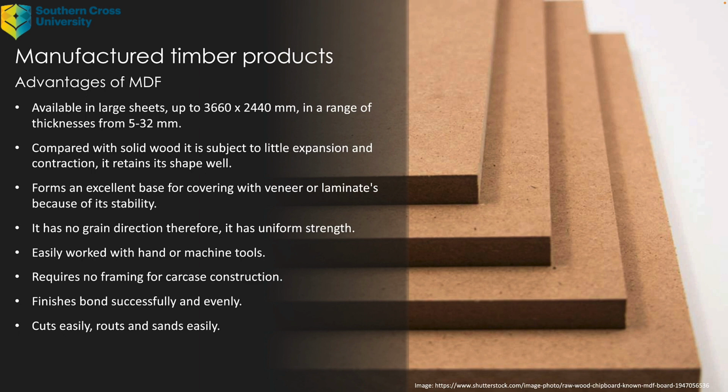Compared with solid wood, it's subject to little expansion and contraction. It retains its shape well. It forms an excellent base for covering with veneers or laminates because of its stability. It's got no grain direction, therefore it has uniform strength. Easily worked with hand or machine tools.